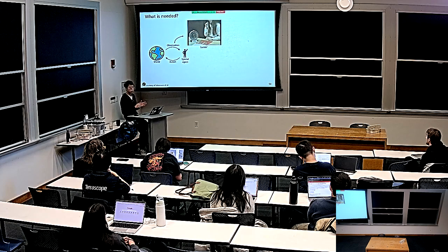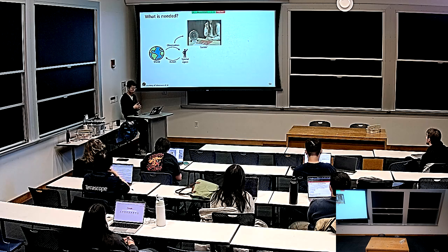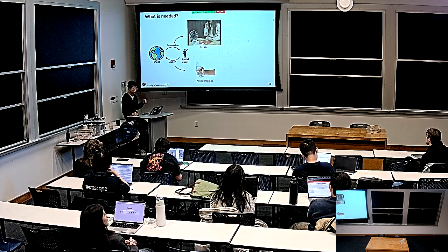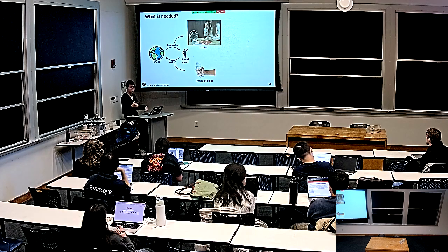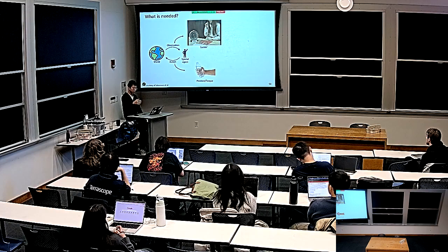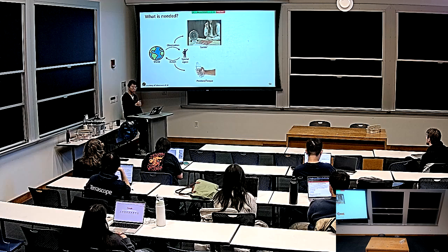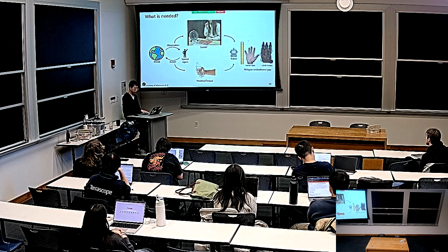Yeah, so now you see how much of a struggle it is to accomplish some tasks without tactile feedback. So we also want the interaction interface to collect this kind of tactile feedback for the robot. And for action, beyond the position, another important action is torque. For example, imagine we are holding a bottle. If I just give you the position of the hand, and you don't apply force, the bottle is just going to slip away from your hand. So that's why torque is also important in action.